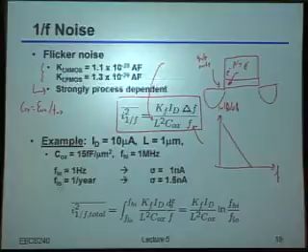Okay, so you said that the threshold gets more constant. I guess what you mean is it's more constant versus the channel length. Unfortunately, that's not quite the exact effect here, although there's a related effect. By the way, what happens to the capacitance of the device as you increase the channel length?